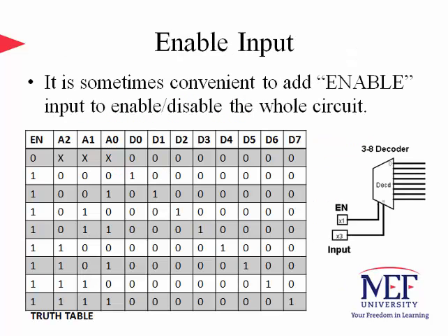In logic circuits, a designer who implements a function or a module usually puts an extra input port on it so that he can enable or disable the functionality of the logic circuit. This way, an external user of the module can switch on and off the functionality depending on the need. Here is an example of a 3 to 8 decoder with an enable input. The truth table clearly manifests the additional row on top that shows the output when the circuit is disabled.